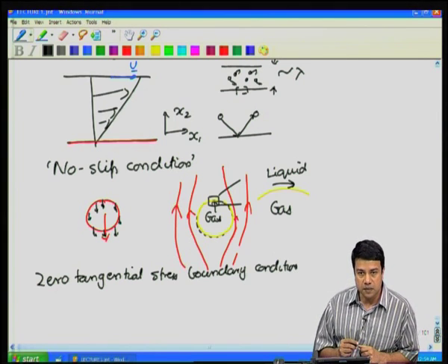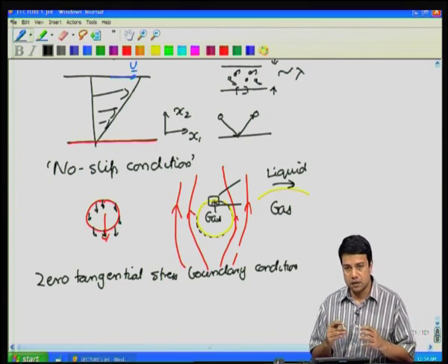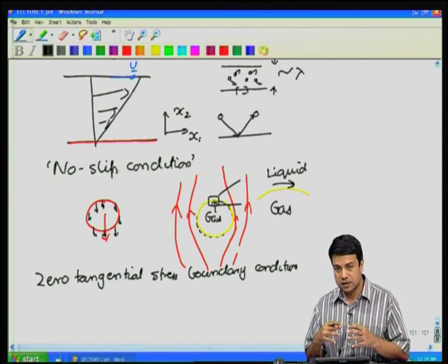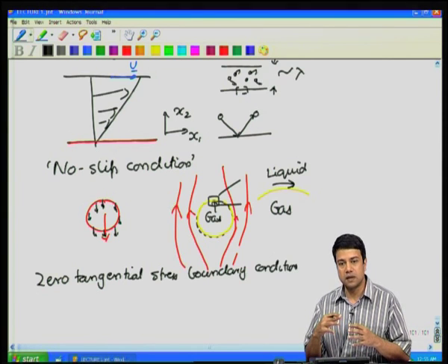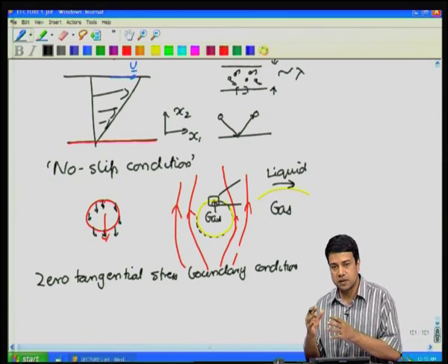And the difference in normal stress, the surface itself can exert a normal stress, and that is what is called surface tension. The difference between the normal force per unit area outside and inside is equal to the coefficient of surface tension times the sum of the principal curvatures.